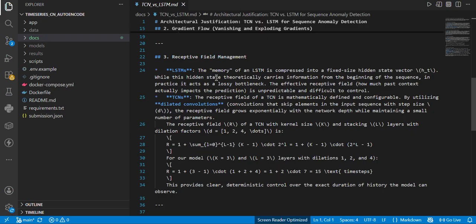However, when it encounters an anomalous sequence, it struggles to reconstruct it, resulting in an error spike. To prevent false alarms caused by temporary noise, we apply an exponential moving average smoother with a span of 10 to our raw signal.